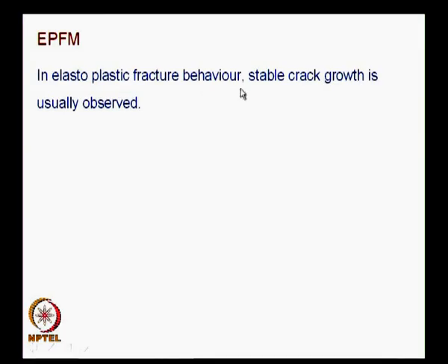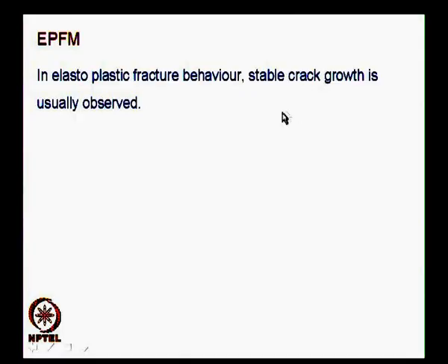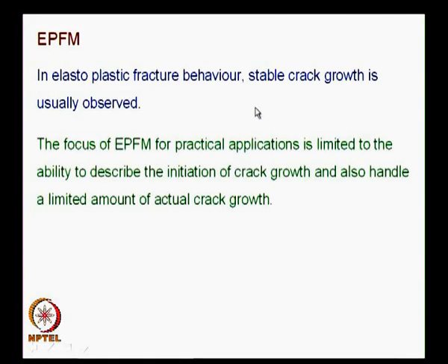In elastoplastic fracture behavior, stable crack growth is usually observed, and I have said if there is crack growth, unloading takes place. So, you have to find out to what extent you can apply the concepts of J. The focus of EPFM for practical applications is limited to the ability to describe the initiation of crack growth and also handle a limited amount of actual crack growth.